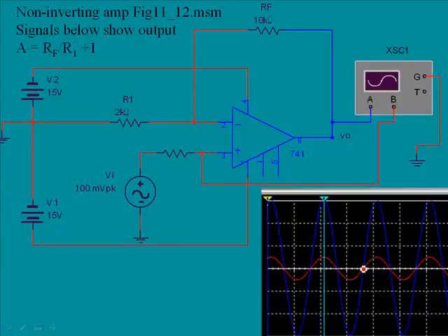And what you might note, this is a screen capture of the oscilloscope readout, and we're on a scale of 200 millivolts per division, and so since this is coming in at 100 millivolts, we would expect that to be exactly half of 1 square, and that's what it is. And you'll notice that this value has nothing to do with it. This actually is the RB value, which can be ignored.